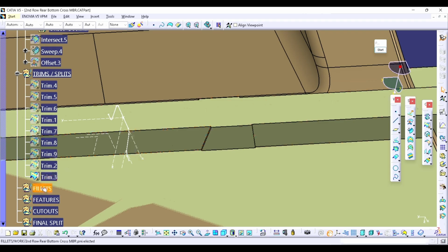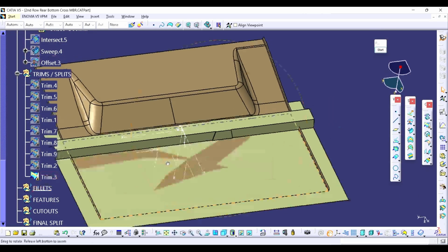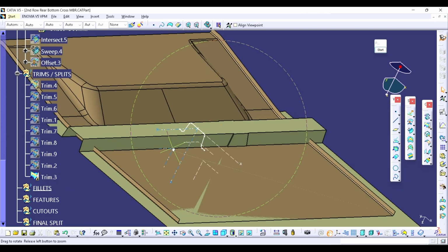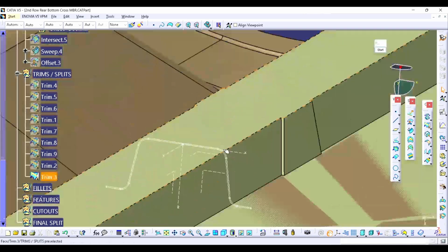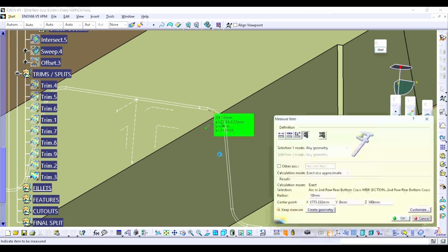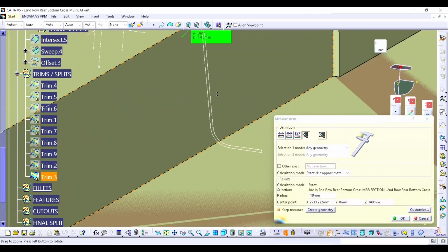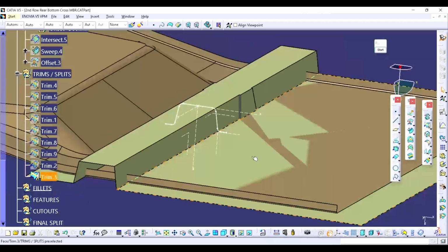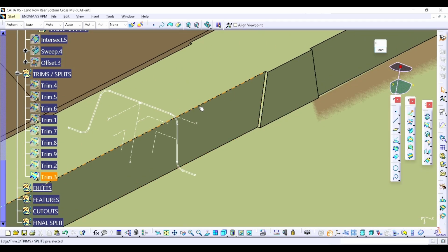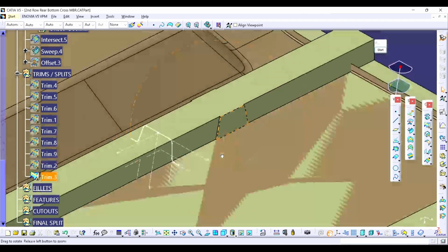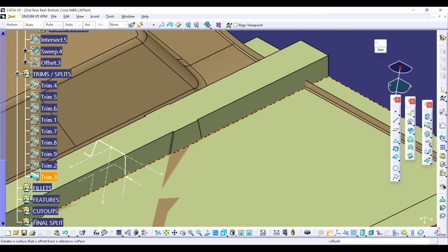Now we are going to provide the fillet. So define the fillets. Okay, so I selected the define the fillets. Now provide the fillet. So let's check how much fillet is there. So the 10. Okay, and what at the bottom? So the bottom is also 10. So before providing these edge fillets, we will try to provide the fillet at this emboss or strengthening bead.